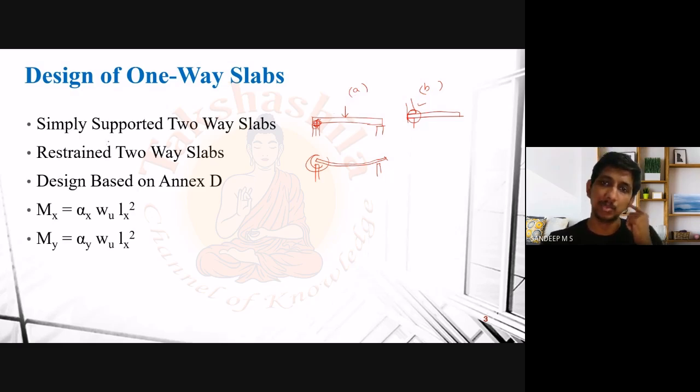So we have different procedures to be adopted in both these cases. The first thing that you have to understand is that in the practical field, you have to check whether the condition will be a simply supported case or a restrained case. Okay, and based on that you have to select your procedure. So we have two methods. One is for simply supported two-way slabs, and another one is for restrained two-way slabs.